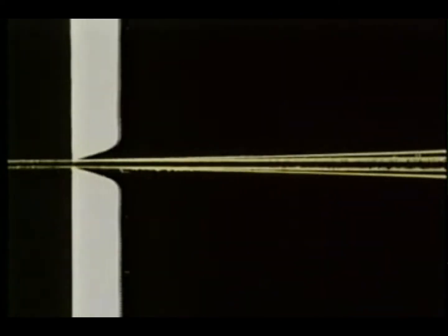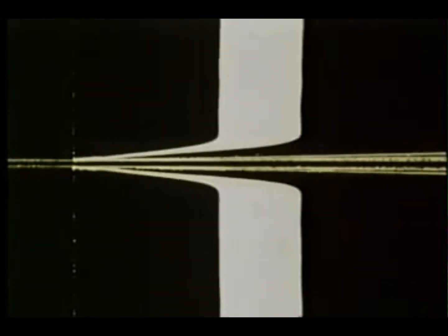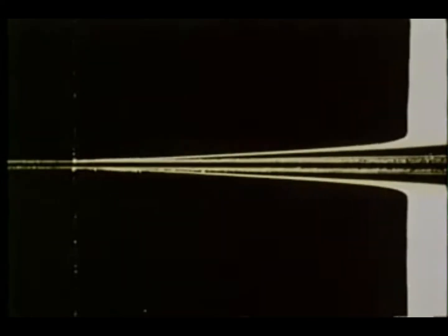We have seen the behavior of two-dimensional boundary layers on a flat plate in a uniform velocity field. So far, the pressure gradients in the flow direction have been negligibly small. However, in most flow situations, there are regions of decreasing pressure and regions of increasing pressure in the flow direction. We will examine these two flow situations separately. First, the case of a decreasing pressure or favorable pressure gradient in the flow direction. We will use this 2-to-1 flow contraction and watch the boundary layer along the flat side.